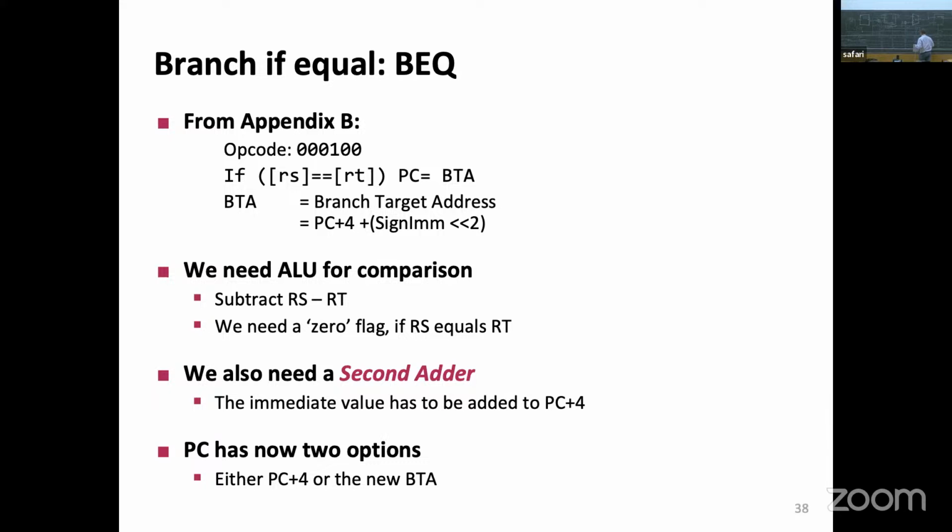And then I take this result, now it gets really horrible. And I take this guy all the way back, and I come back. And now I have two choices for the next state of the program counter. It's either PC plus 4, or we have another multiplexer here. And this one selects, let me see, this is PC4. PC4 is this. So this is either 0 or this is 1. And the address is called branch. Now, unfortunately, my clever way of writing did not allow me this, so I'm bringing branch here. Sorry about that. Bad design.